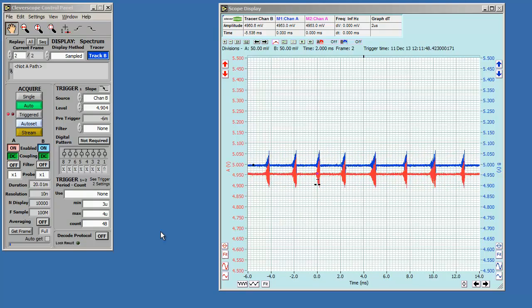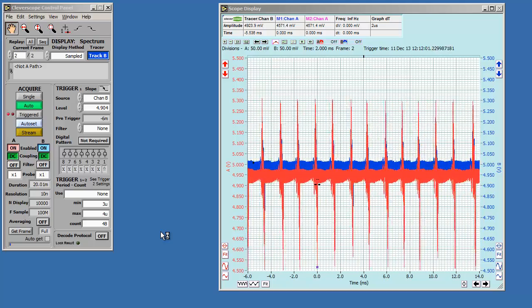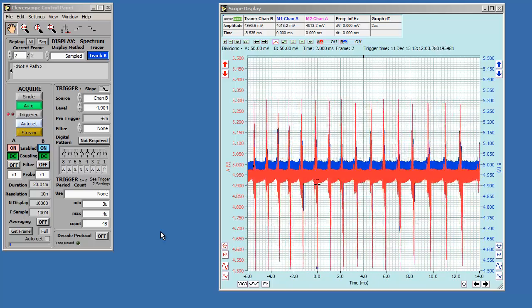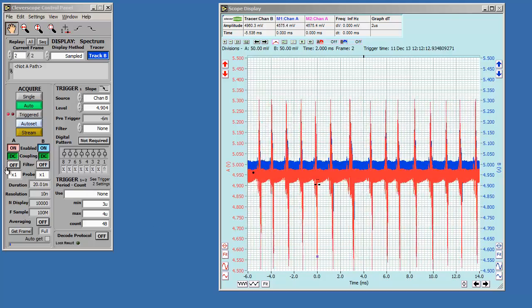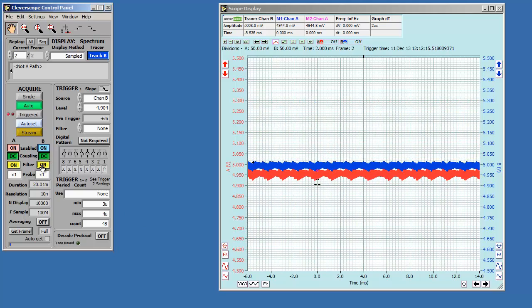As you can see, it's about 5 volts output, and we can see little switch transients which are actually quite significant, about 50 millivolts peak, and this is without a load. Now I'll turn the load on and we can see much more. We can see 300 millivolts of peak noise. Now we can improve the look of the signal by applying the filters, so let's do that. Okay, so now we have a filtered signal and we can see more clearly what's actually going on. Now we're going to start the FRA by turning on the spectrum and FRA control panels. Let's go into View and turn on the spectrum display.